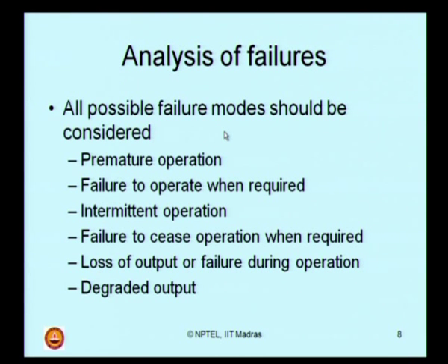You may ask me a question, so what are the different possible failure modes which I must consider in my FMEA? I am giving a list of examples here. Premature operation, for example, you want a valve to be open when the temperature reaches T degrees Celsius, but is there a possibility that the valve may open before the temperature is T degrees? Premature operation.